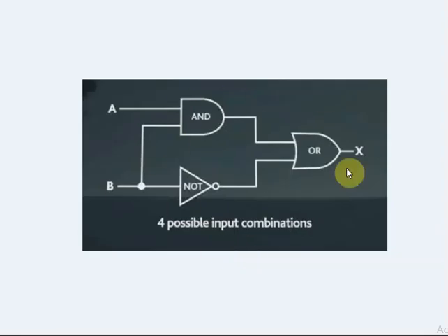Now you see this gate, how many inputs, right? We are not counting with these lines, right? Here 1, 2, 3 lines, but you have to see the variables, right? Only two different signals. Now if you put A here, then we need to consider it as one signal. Then the truth table is for 0 and 1. Here A and B, two different. So then 2 to the power 2, there will be 4 combinations, right?